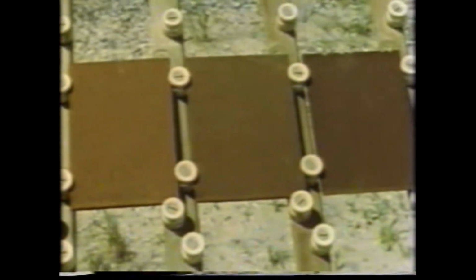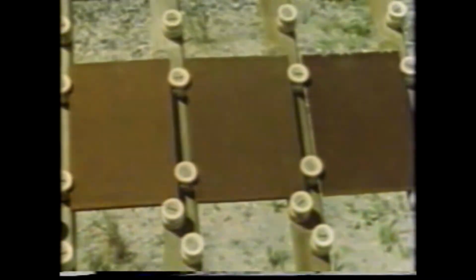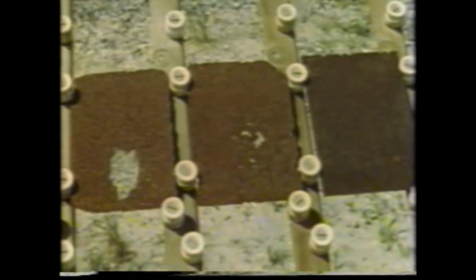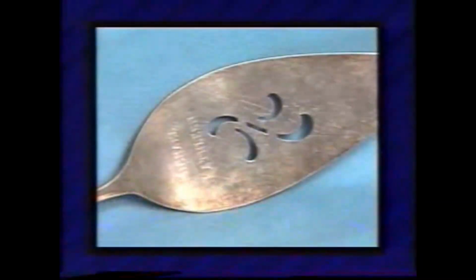In some metals, such as steel, general corrosion produces a somewhat rough surface and removes a substantial amount of metal, which reacts with the environment and produces a loosely adherent porous coating of corrosion products. Other reactions, like the tarnishing of silver in air, produce thin, tightly adherent protective films, and the metal surface remains smooth.